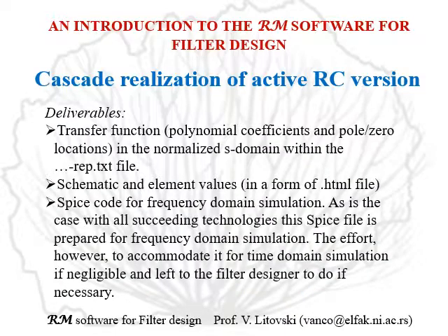And again, one gets a report file containing the whole process of synthesis, the HTML file containing the schematic and the whole process of synthesis, and SPICE code for frequency domain simulation, which may be, with a small effort, transformed into a SPICE code for time domain simulation.